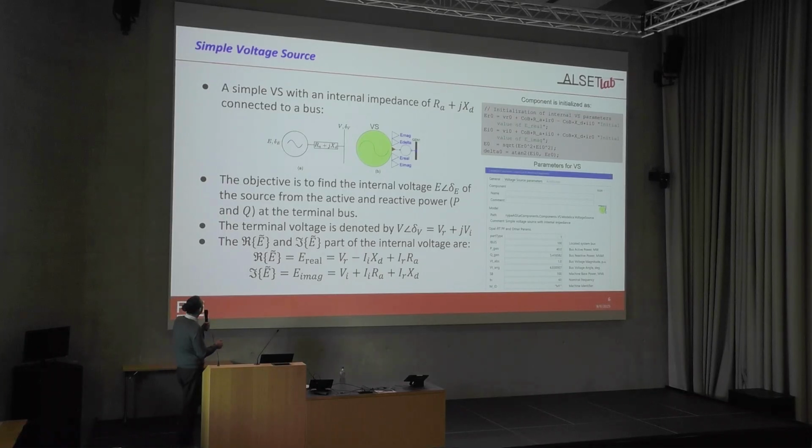So for you to understand, basically you have to build a voltage source model, and in the voltage source model what you're going to do is have an internal impedance, and if you don't control anything, you have to calculate what this is. And this is important because figuring this out makes it possible to figure out how to initialize correctly a controllable voltage source and then provide all of those initial values back into the controls.